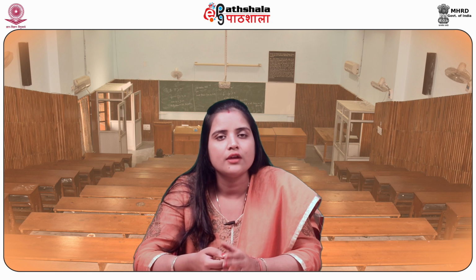This was demonstrated in the year 2007, where E-beam was used for double patterning to fabricate 15 nanometer half pitch zone plates. In this study, the 15 nanometer feature could be easily resolved, whereas a 30 nanometer pitch could not be achieved. This was caused by the scattering of secondary electrons from the adjacent feature.